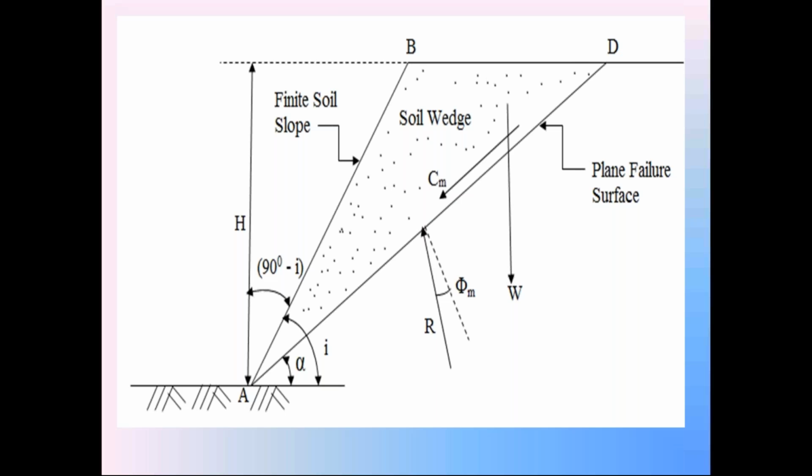So this is the diagram. This is the finite side slope of embankment AB. Please everyone check this diagram. It is also prepared on the graph sheet. Please everyone follow this procedure. First, we prepare this embankment plan on the graph sheet with this side slope according to a convenient scale.